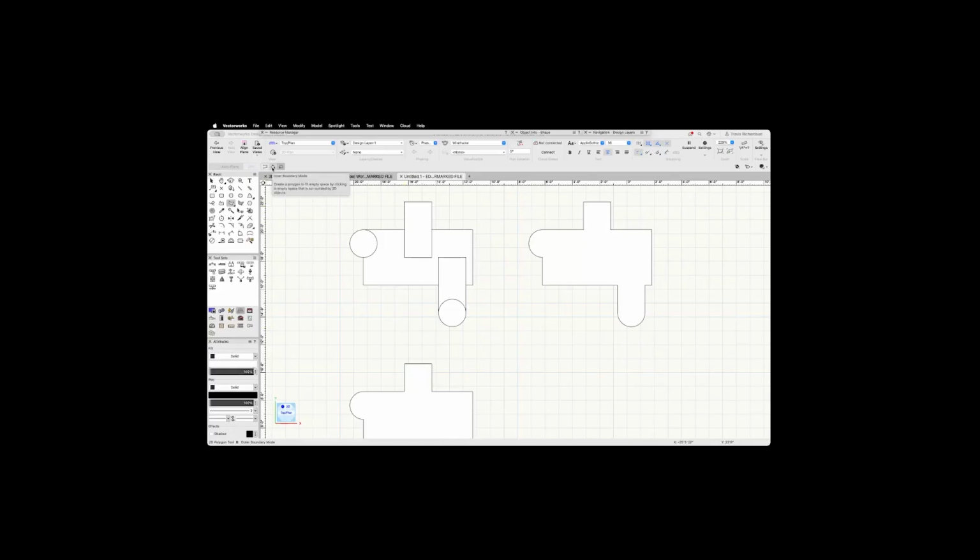The next mode is the inner boundary mode, and it's going to essentially create a new polygon, but doing the opposite of what the lasso tool did. So this one looks like a little paint bucket. So we're going to select it. So we've got inner boundary mode. I'm going to come over to my shapes right here and click on that. And you can see it has created a new polygon that is just the internal shape of that polygon.